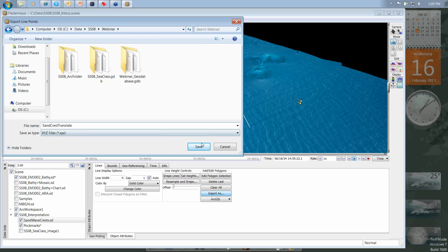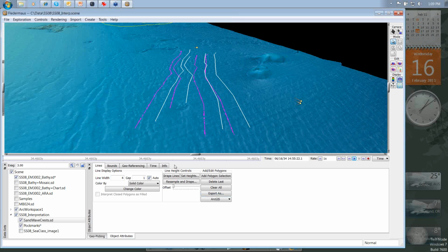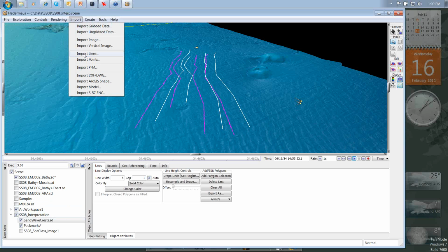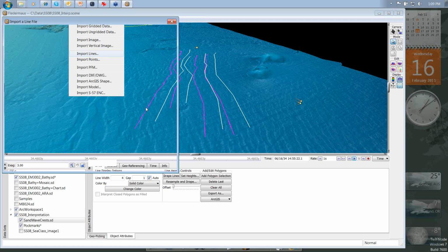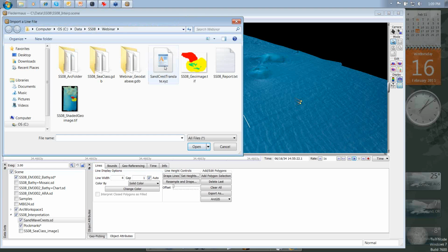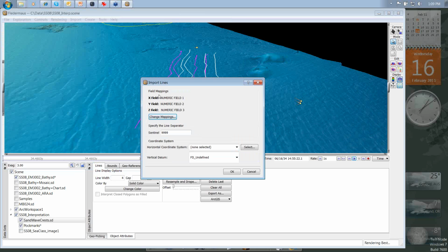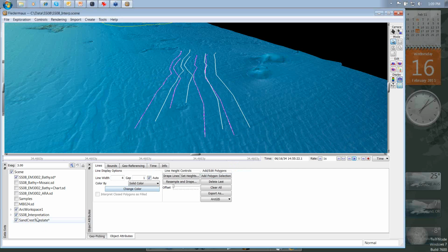I guess we don't really edit tables, so you would do the table editing in ArcGIS. Am I right there? Yeah, there's no continuous dynamic connection to the GIS. If you push data into the GIS, then there's a feature class in the GIS that's now separate from the SD object that's in Fledermaus. So if it gets modified within ArcGIS, those changes are not going to be seen until it's re-imported back, and vice versa. There's not a continuous connection. You'd have a significant performance degradation if you tried to do that.